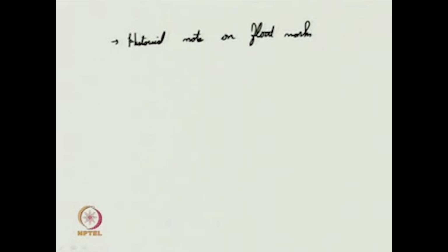You have to note the various flood marks in the channel. During the peak rainy season and peak flow of the river, this was the mark of the flood at that time. During the lean period, this is the mark. You can either capture them in photographs, or you can do a survey related to the marks. You can just obtain it as data.